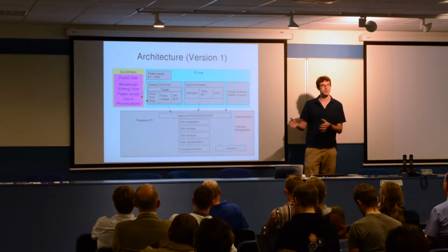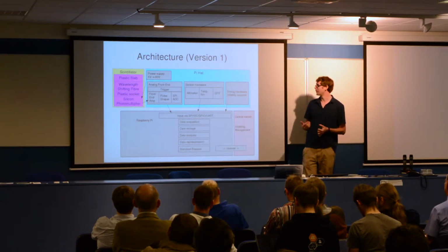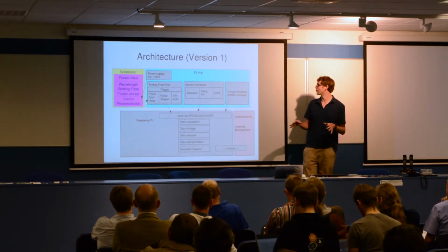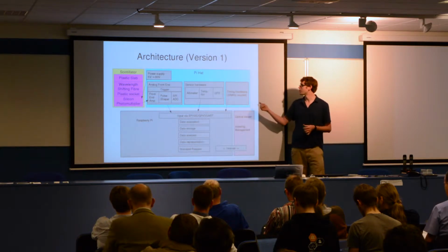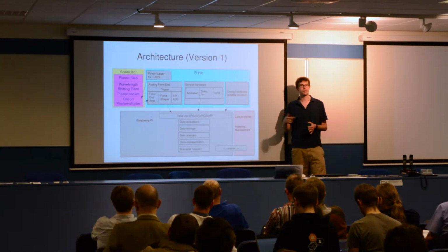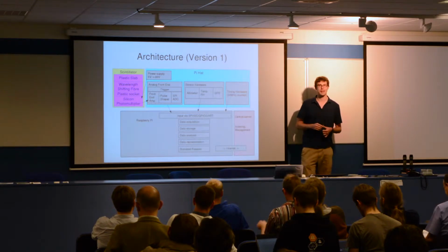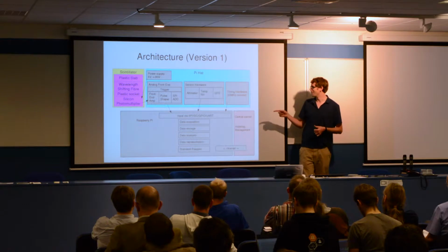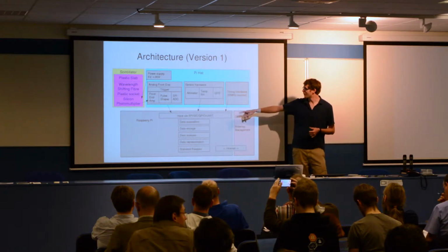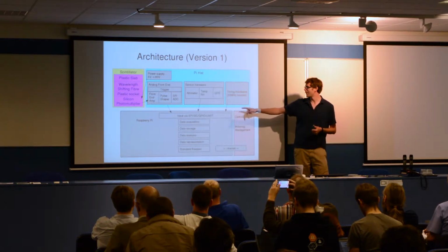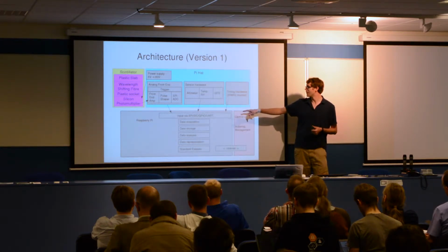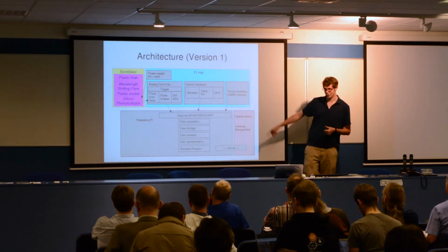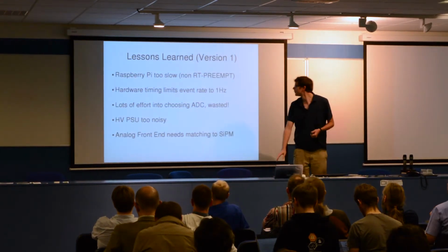And the GPS is obviously to give us position, but more importantly, timing, so that we can correlate 2 or 3 or 4 or a whole network of different devices. In our first version, we implemented a hardware counter, so we had a 33 megahertz 32-bit counter that we just ran with an interrupt when we detected an event. This gave us some problems. All of this was connected via various buses, so we used SPI, I2C, GPIO, and UART to connect that to the Pi. And then we simulated having a central server to put all the data in.